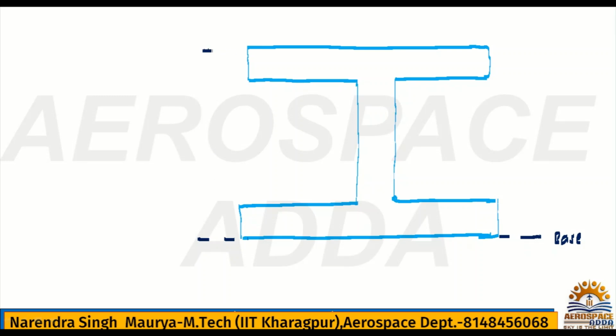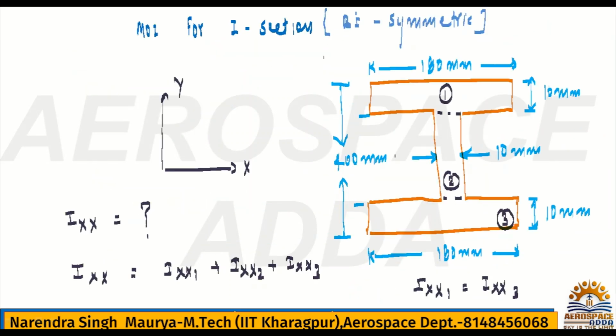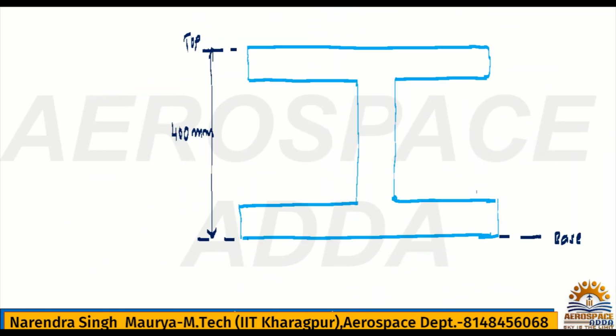If you check from this top, this is the top, right? And this is the base. Top to base, what is the height? It's 400 mm. See the problem, it's 400 mm. This is the top and this is the bottom basically, and this bottom is nothing but your base. So all CG you have to calculate with respect to the base only, with respect to the bottom only, right?